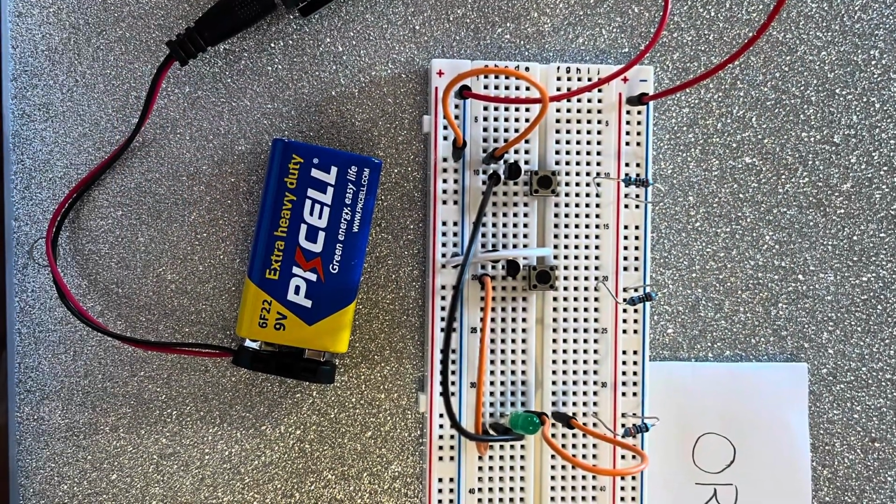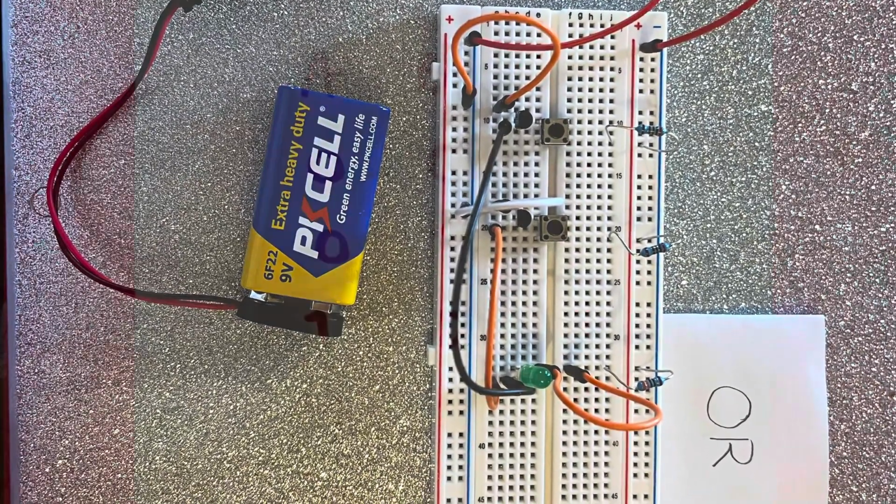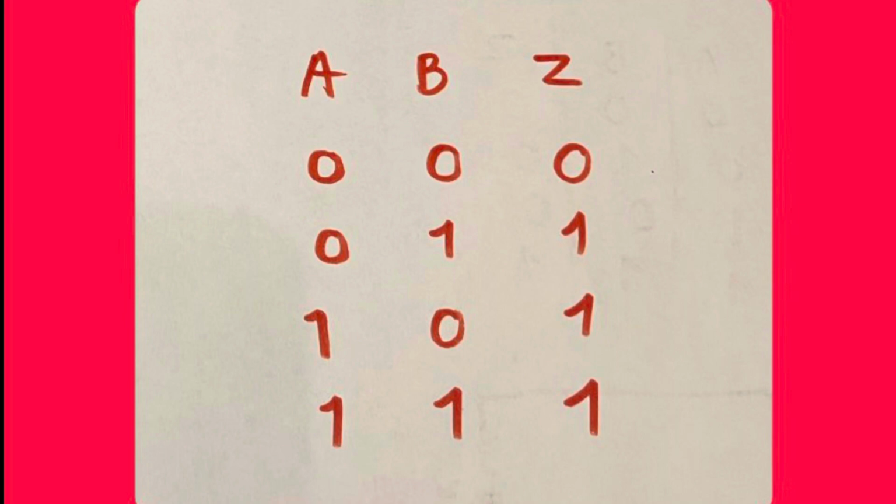So finally, looking at our OR gate, as the same word OR says it, we would need one input to be closed or the other one to be closed in order for our output to be 1. So for our first row, as you can see, both inputs are 0. So that would mean that our output would be 0 since none of them is actually closed. So for our second row, you can see that our B input is closed. So that would mean that one or the other is closed. So that would mean that our output would be 1.